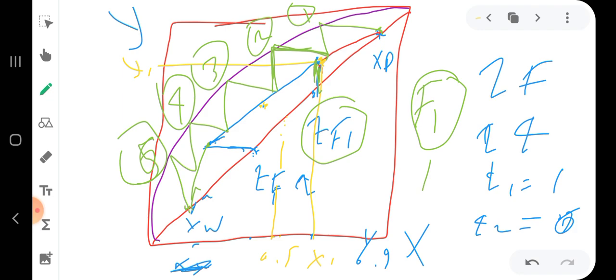And if you are interested to know the stage for the second feed, you see here, this is the Q line of the second feed, and it is in the fourth stage. So the fourth stage is the stage where F2, the second feed, is going to be introduced. Okay, and that's it. That's the case where you have multiple feeds.